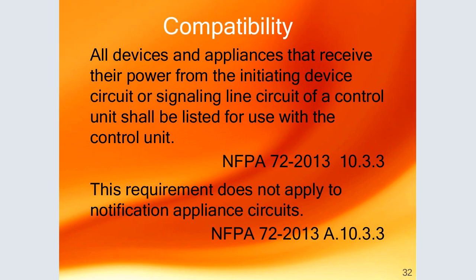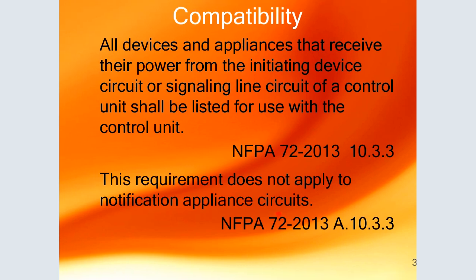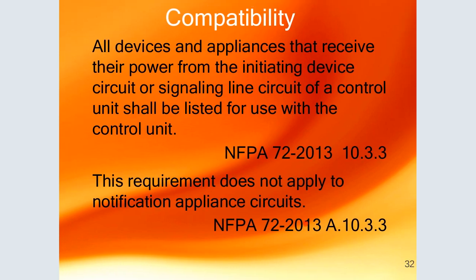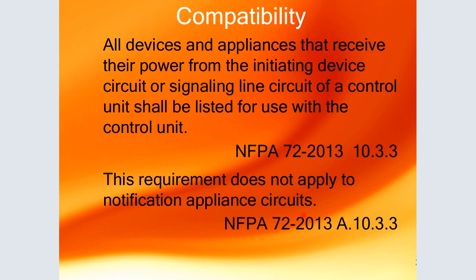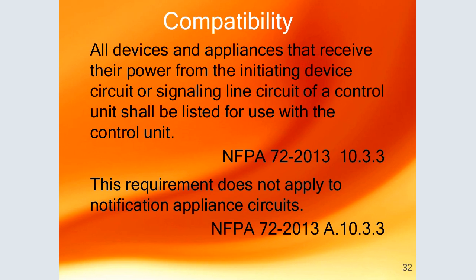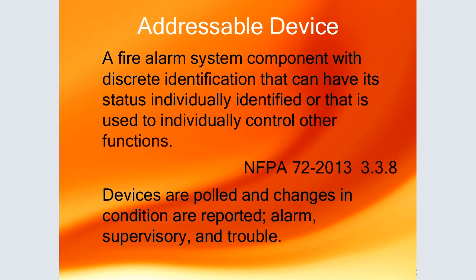Then all devices, that is the compatibility. All devices and appliances that receive their power from the initiating device circuit or signaling line circuit of a control unit shall be listed for use with the control unit. This requirement does not apply to notification appliances and circuits.